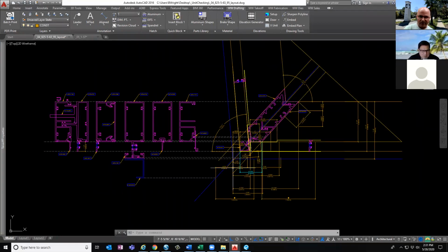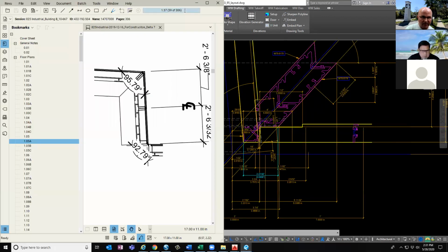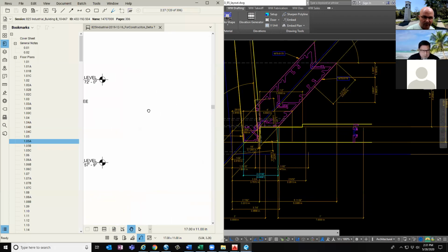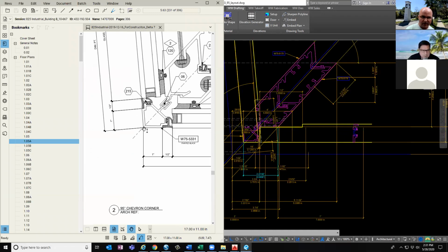Now, what I'm seeing here is that when this layout was done, the dimension point was actually 1 inch out past the face of the glass. So that's a little bit farther than what our actual current shop drawing is showing. If I go to my corner detail here and verify what my dim point is showing, 2 on 563, the dim point's actually right at the face of the glass. So that tells me that from the time we did prototypes, these were done off early profiles. The actual shop drawings were set up slightly different.